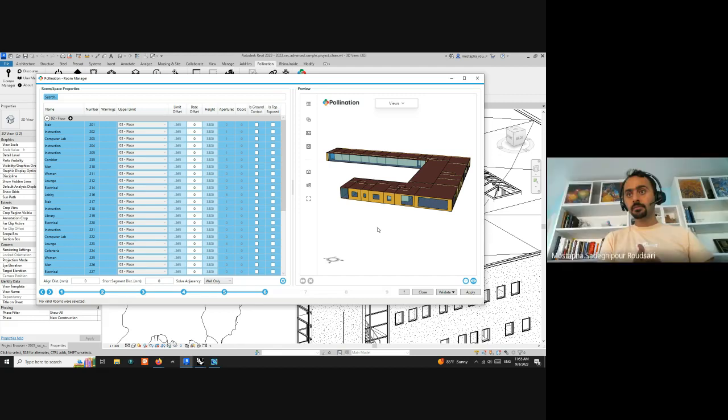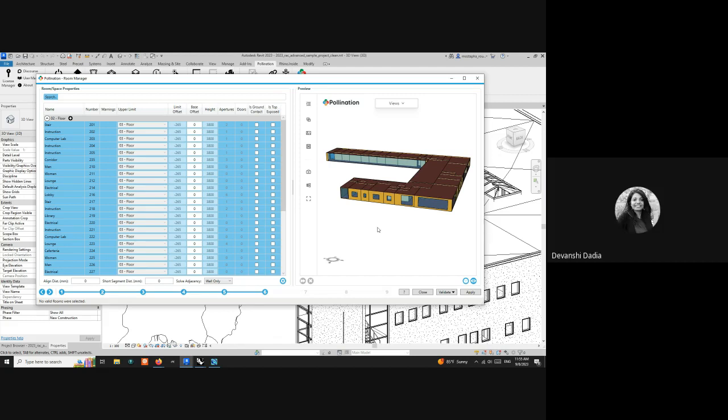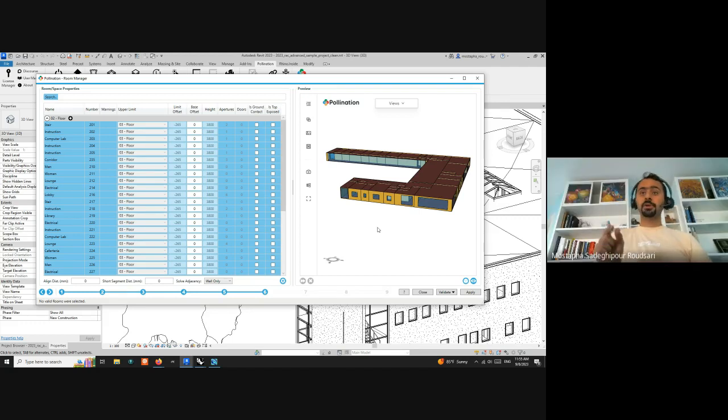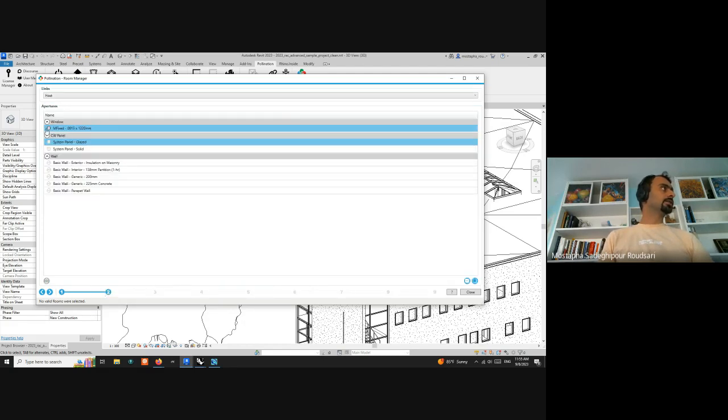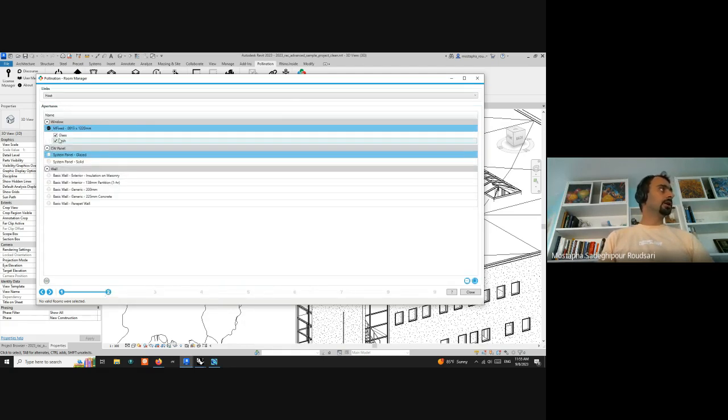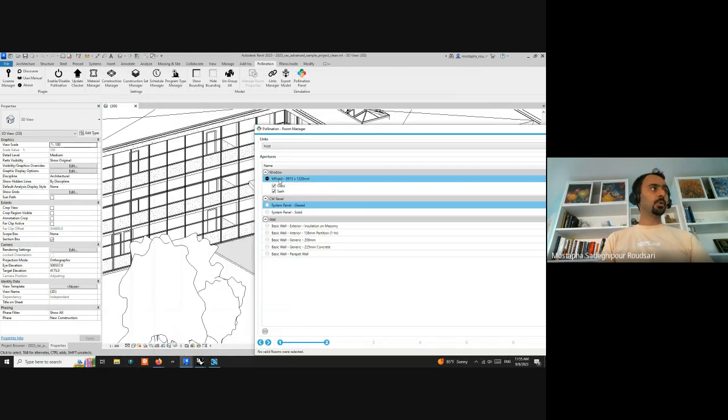Hi, Devanshi. So, what about the frame thickness? Do you think that gets transferred over from Revit to eQuest? As a number, no. So that's the one that I was talking about. So you have control. Let's say here when I have a window, you see there is glass and sash if you build it as a window.